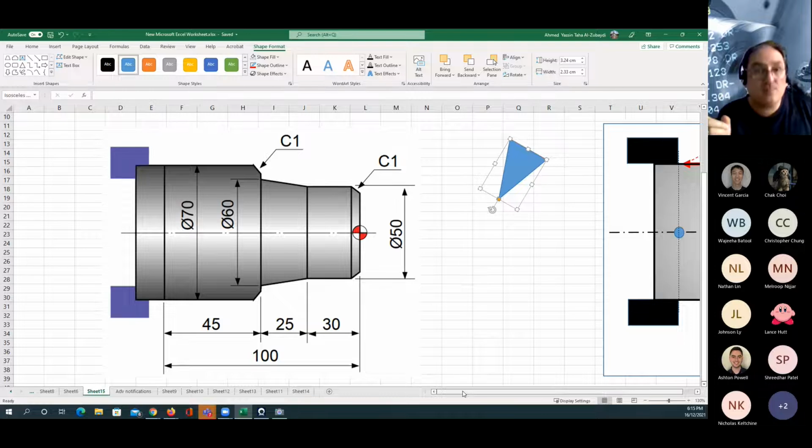Okay, it depends on the cutting tool material, the speed of the cutting, because this will increase the temperature, and the material I'm cutting. So if I'm going to cut, for example, wood, I can go down to 4 millimeters. That's possible. If I'm going to cut aluminium, maybe I need to go less than 2.5 millimeters.